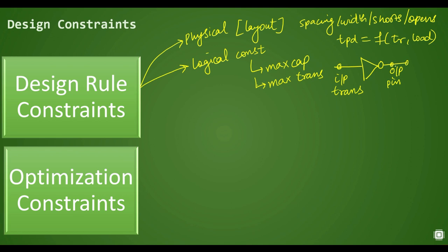So we need to respect these constraints, otherwise we cannot guarantee the delay values, and we cannot guarantee that we are timing the design properly. Hence these constraints are very important. In fact, not only input transition, output transition is also important. Input transition and output transition are constraints which are necessary to be respected to ensure the proper functionality and proper timing of the design at a particular frequency.